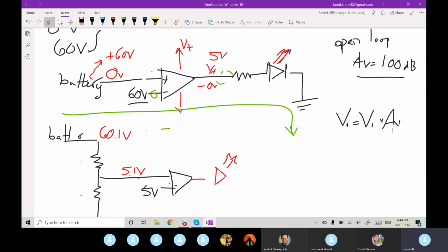Andre, you had something? So typically, when you apply an op amp as a comparator, you don't use an op amp IC, right? You use a comparator IC, because it's kind of a dedicated op amp.